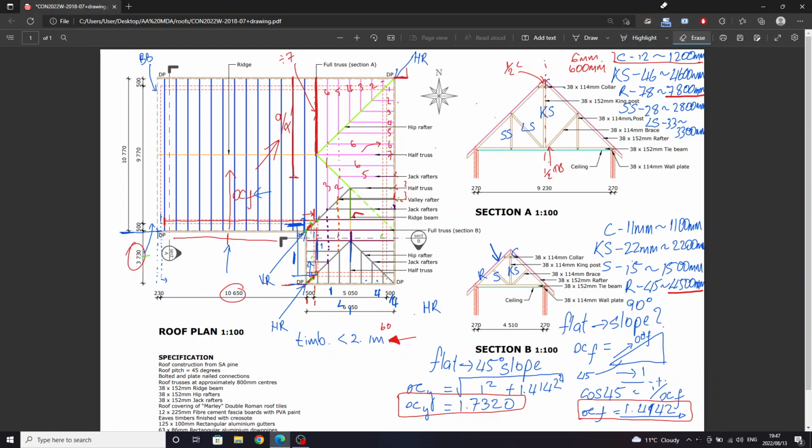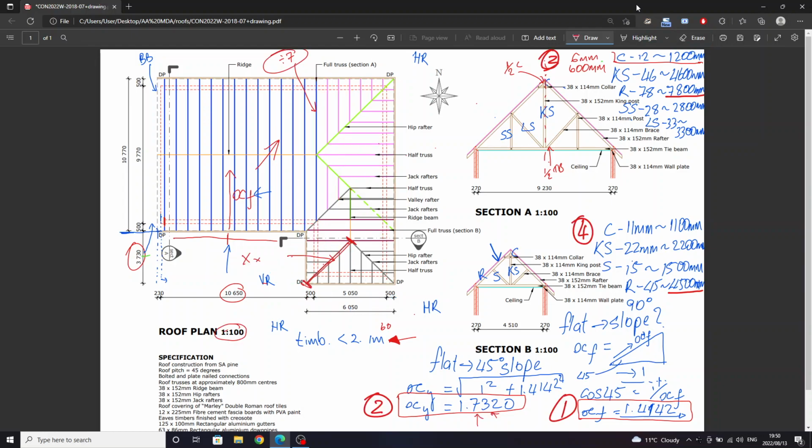And it's X length on flat. I've got my factor 1.732, and you have your answer instantly. It's very easy like that. And then all you do is you times your answer by 3. Okay? And the reason you can times it by 3 is, despite this being a valley rafter, it does not discriminate. It says, well, it is timber, it still runs this way. It only becomes a valley once you add a covering to it. But it is all the same to the timber.